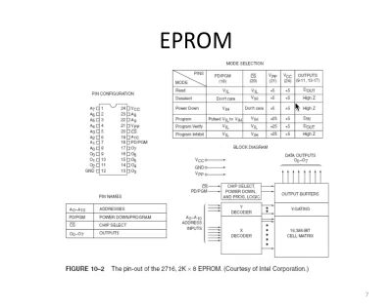In this particular chip, this is a 2716. That's the model number. It is a 2K times 8 EPROM. Now, we often use this representation. This is to say this chip outputs 8-bit data, and it has 2K locations. So essentially, this chip has 2K bytes stored as the content.